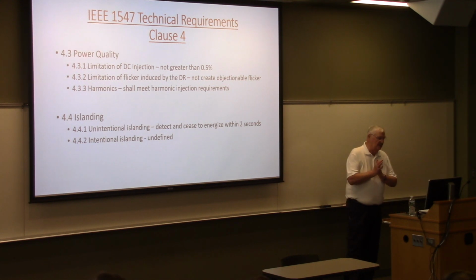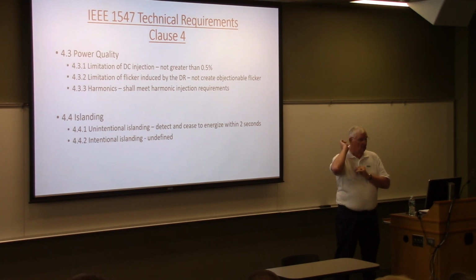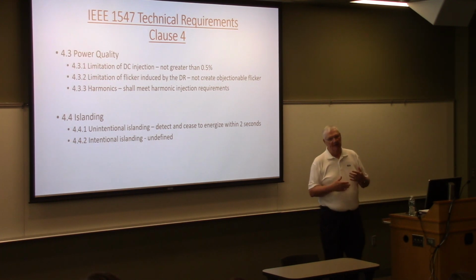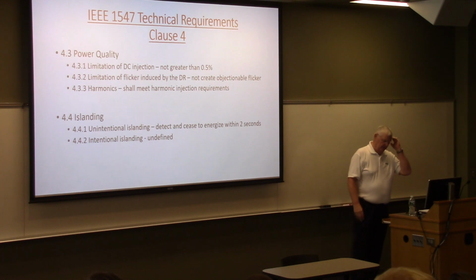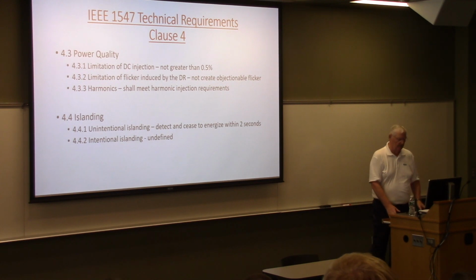The basic presumption on electrical equipment is they look at immunity and emissions for conducted and radiated harmonics. So you have to be immune for upwards of 8% harmonic content. And for emissions, depending upon the frequency, you can't emit any more than upwards of 4 or 5%. So that little 3% variance there is what is presumed to give you a buffer for allowing for standard operation.